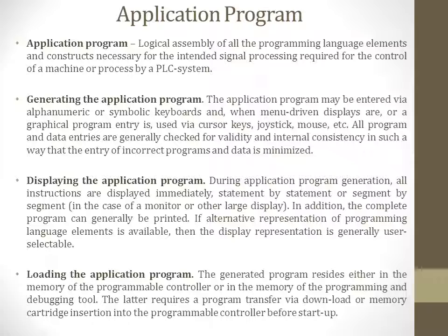About loading the application program. The generated program resides either in the memory of the programmable controller or in the memory of the programming and debugging tool. The latter requires a program transfer via download or memory cartridge insertion into the PLC before startup.